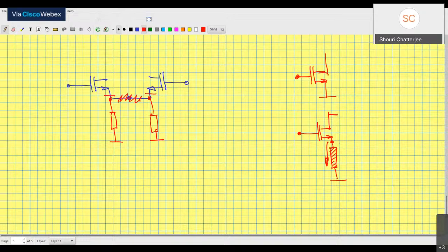You would like to have a current source. However, the general principle applies. If you can find a way to use a resistor over there, please go ahead. Don't use a current source. All right, current source is the most convenient. In RF circuits, for example, at very, very high frequencies, the most convenient is not a current source. In those cases, we actually place an inductor.